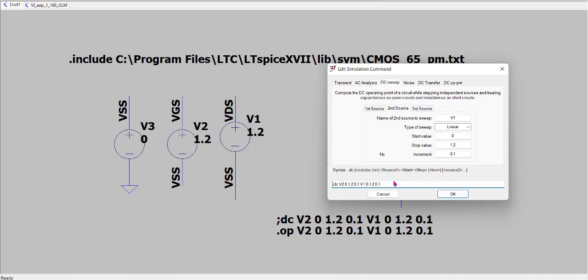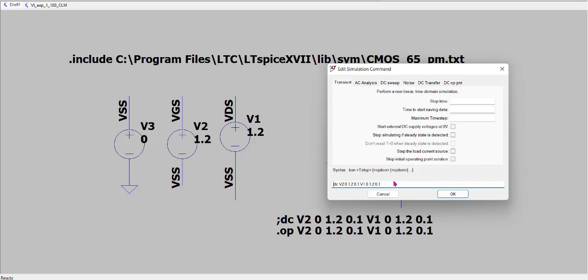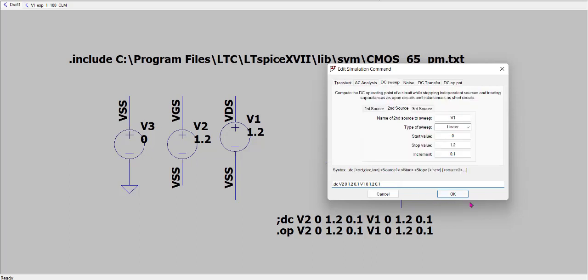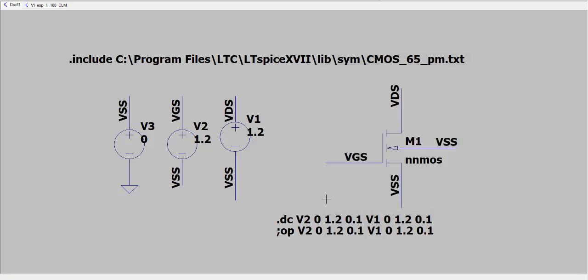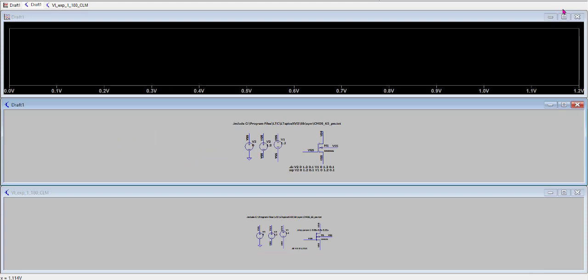So why am I doing this? Because you remember in the transfer characteristic, what is basically a transistor? You vary the voltage at one point and the current at another point varies, right? So basically we vary the voltage at the gate and we get a drain to source current which is varying because of that. So we will try to check that here. I'm not explaining how the software works, I'm simply running it.